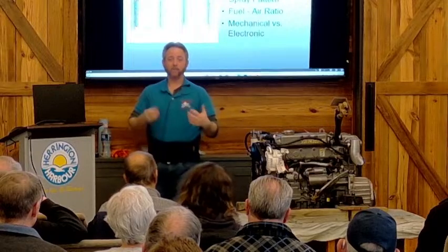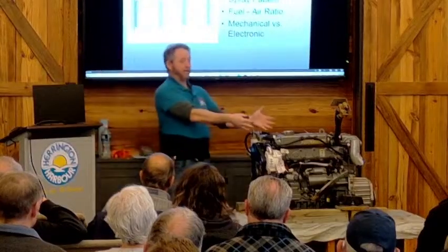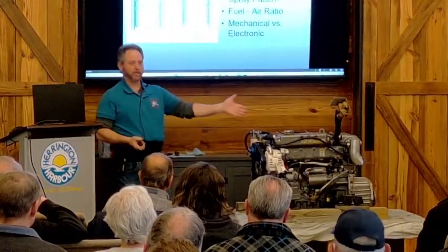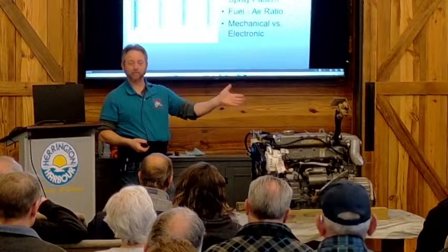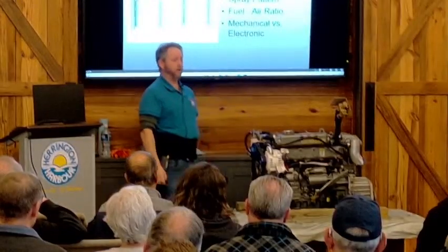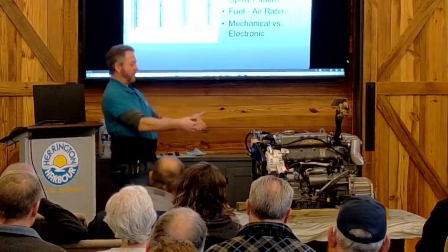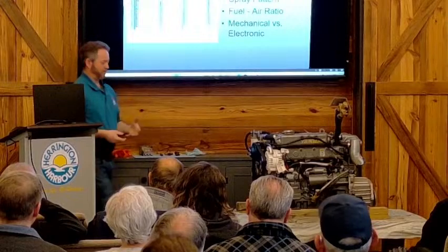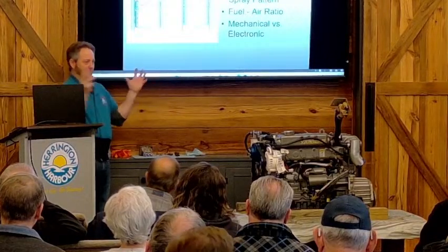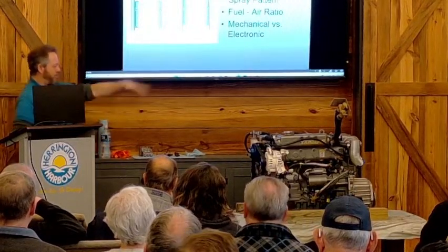And so they designed this engine to run within all those variables. Now, when those variables change, such as it's 30 degrees outside and this was designed to run at a 90-degree outside temperature, then our variables are all out of whack. So this engine is not going to burn nice and cleanly, and it may not run smoothly. It may produce a whitish gray smoke because the cylinders are extremely cold because of the outside temperature. The outside air going to the engine is super cold, so it's not exactly running lean, but there's extra oxygen because the molecules are closer together for the amount of fuel we're spraying in. So it's going to put out more of a whitish gray smoke coming out the exhaust.